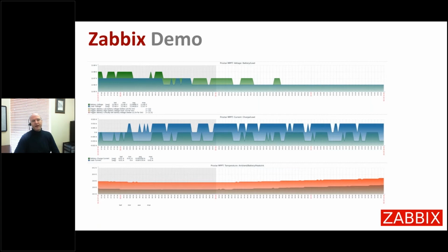If you see that you have 20 sites in pretty much the same area, but one of them is reading a lot of anomalous data that's completely different from the rest of the sites, and everything else is expected to be the same, why is that unit standing out amongst its peers and not performing? Maybe there's damage to a module. Is there a battery cell failure? Something is different about that. And you'll see that those pieces of information start to jump out when you've got all of this data available to you. So it's extremely powerful.